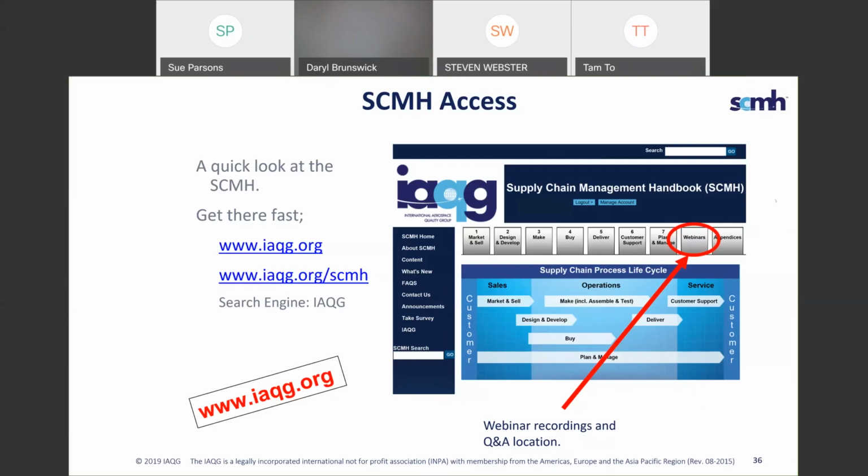One other comment to add on to that is that the severity comes from the product risk analysis and the DFMEA into the process. That is a team effort on the DFMEA, but you shouldn't overlook pulling product severity numbers into the PFMEA. It's one of the links.